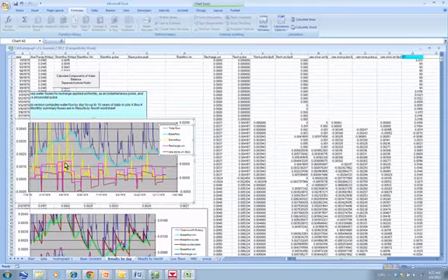You can see it's kind of a step function. And what it's doing is, in this separation, there's a turning point here and a turning point here, and it's assuming that the recharge is uniform between those turning points. So it's kind of steppy. But you can see we had this big rainfall here, probably in the mid-spring, and that caused the recharge to be this amount. The recharge is shown over here on this scale, and it would be 0.005, and the units are feet per day.